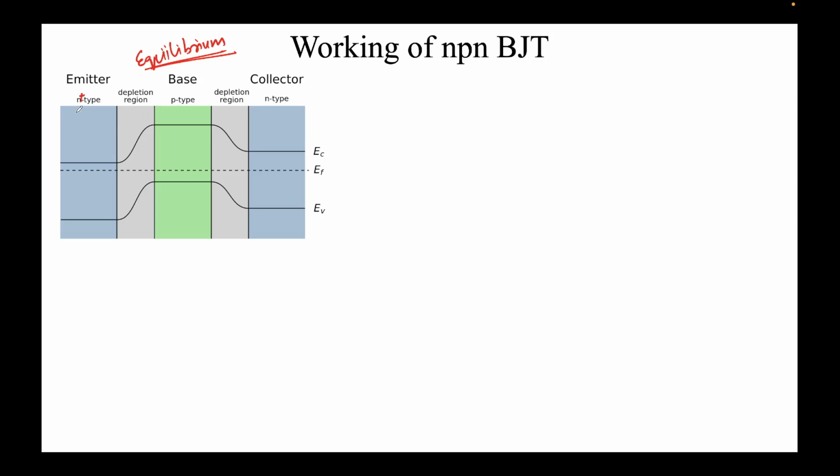You know that because this is heavily doped, and we had seen those expressions due to charge neutrality, like Na times xp equals Nd times xn. Refer to your p-n junction session, I believe the fourth session. So depletion is generally primarily on the base in this emitter-base junction.